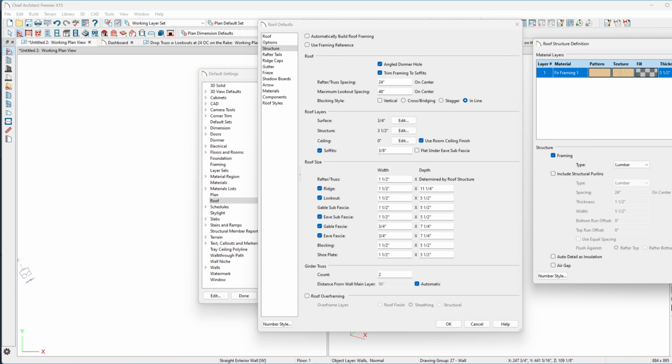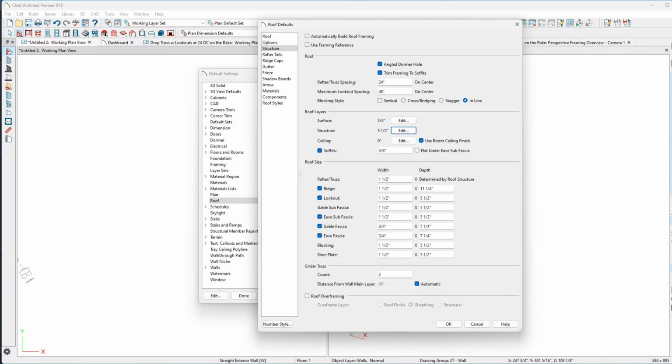I make my top and bottom chords on most of my trusses 2x6, so you can actually get up there and store stuff, and your roof is just more sound and solid. If the truss company wants to reduce that, and they've discussed it with you, then fine. We can automatically build the reframing as we go along.